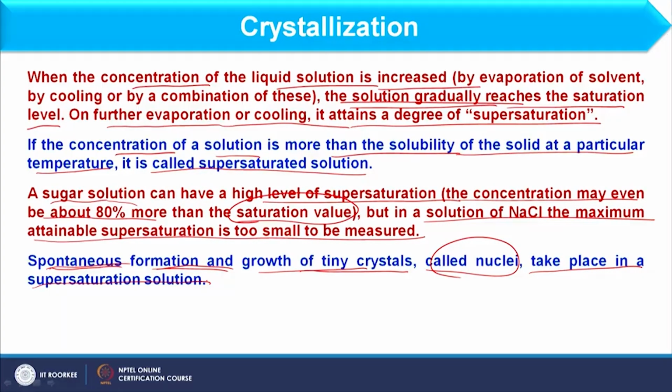Okay. But a crystal has a definite size, right. Initially it is not in the form of a crystal, it is very small particles. Or we consider that as tiny crystals, in other words, nuclei. So initially very small particles are formed, and then there is continuous deposition of solute over the surface of the tiny crystal. We get definite size crystals, but it basically starts on the nuclei, right, and that occurs at supersaturation condition.